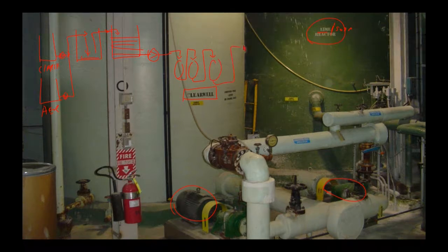And from the pressure filters and carbon filters, we're going to go into ion exchange units. So we're going to have a cation exchanger. Then the water is going to go through an anion exchanger. We'll have a mixed bed demineralizer on there, and we'll get to that a little bit later in class today. And then it goes to a feed water storage tank in the plant where I worked, or it could go to a deaerator, followed by the boiler feed pump. You get the idea, you know the drill. Okay, so this is makeup water.